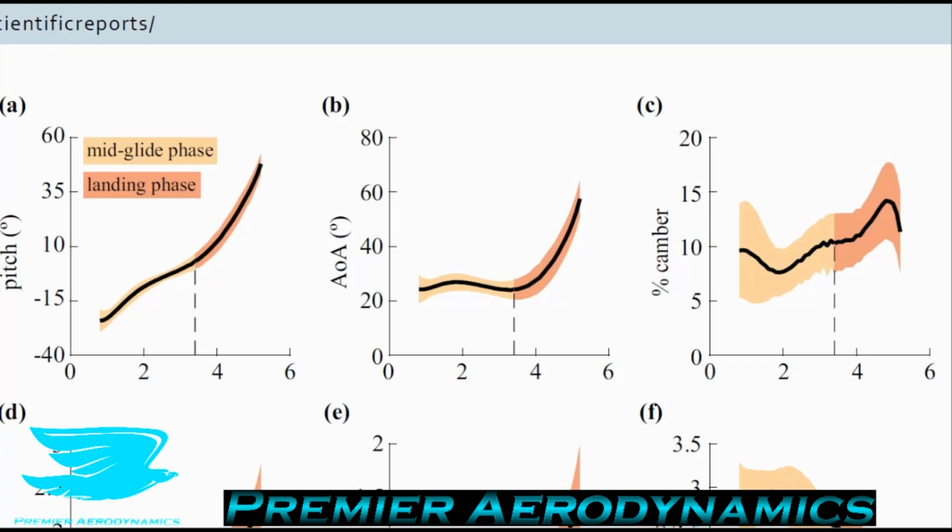Usually you'll get the highest lift at very high angles of attack just before stall. But at this point, you're getting a very high drag production as well. And that's what's happening here as well. That makes sense. And the reason why they're producing the greatest lift to drag ratio early on in its flight is that it's trying to get up speed to begin with. So you want to have a low drag coefficient, and it's also just gliding around, just a stunted glide. It's not trying to touch down or anything like that.